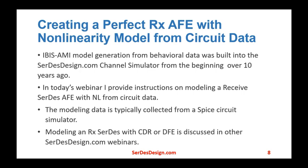In today's webinar, I provide instructions on modeling a receiver SerDes AFE with nonlinearity from circuit data. The modeling data is collected typically from a SPICE circuit simulator. This discussion is for a receiver SerDes with an AFE with nonlinearity, but with no CDR or DFE. Modeling with a CDR and or DFE is discussed in other SerDesDesign.com webinars.